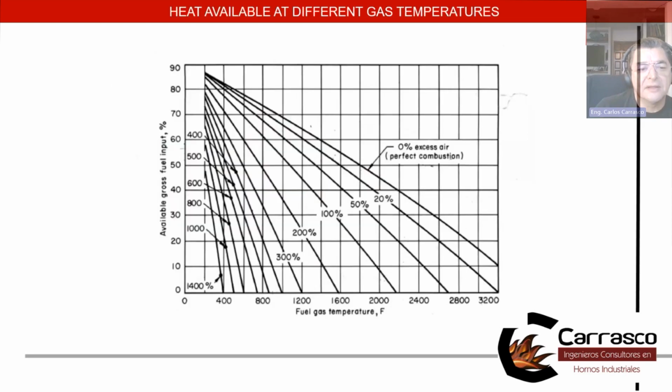in a system. When I have direct combustion, I have to measure the flue gases at the exit of the furnace. And depending on the temperature of the flue gases and the combustion control I have, I will be able to know the efficiency, how much heat I'm going to lose during that heating process.